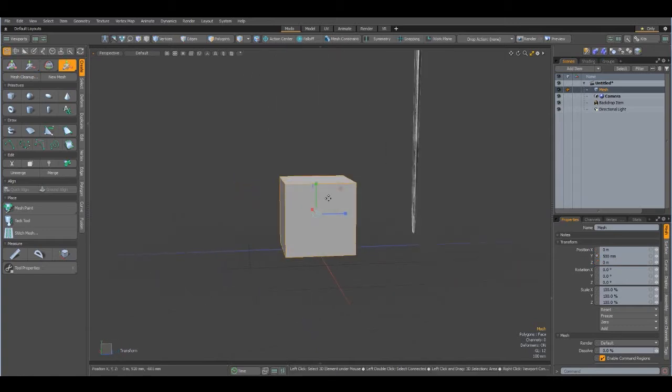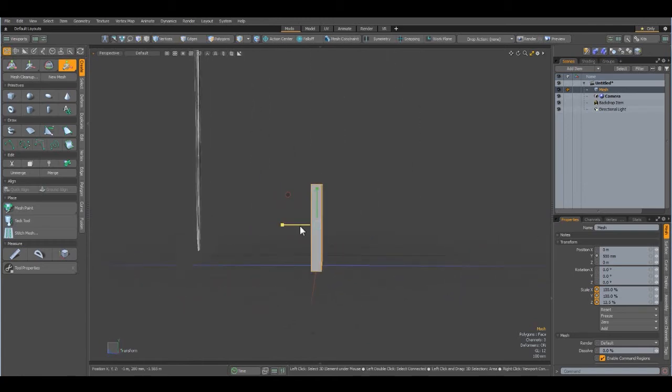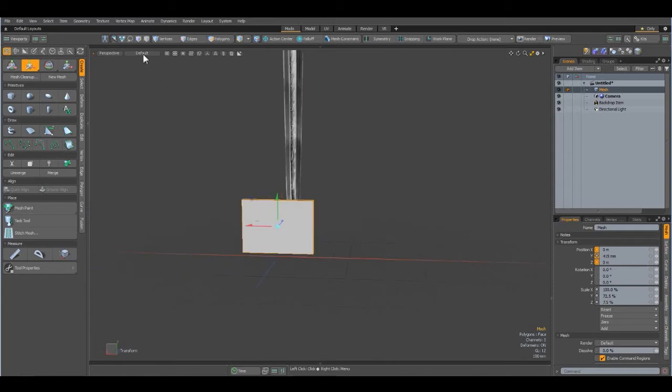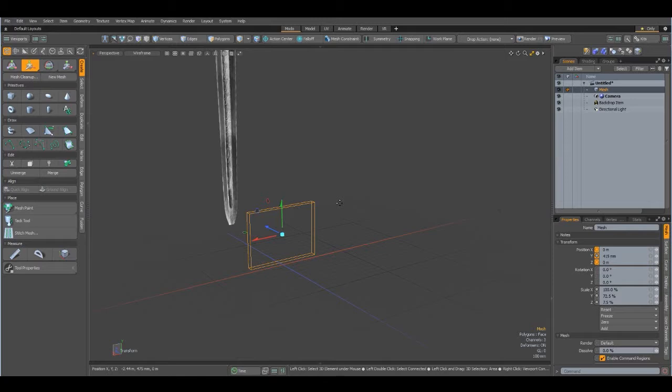We'll first make it thinner on the z-axis. There's no point of reference here, so it's just guesswork for what feels right. For the rest of the shape we can use the ref, so we'll switch to wireframe mode and select edges at the middle top panel.